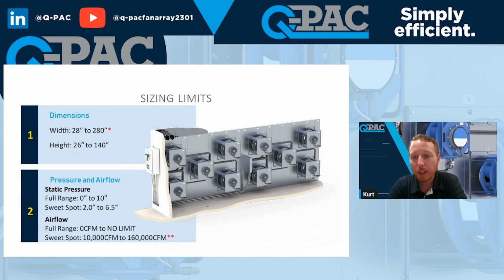Airflow wise, we can go from 0 to no limit. We can stack as many fans as we want. You can buy as many systems as you want and put them in the same common duct. Our sweet spot, really 10,000 CFM to 160,000 CFM. 10,000 CFM because that's when you'll get into more than one fan.